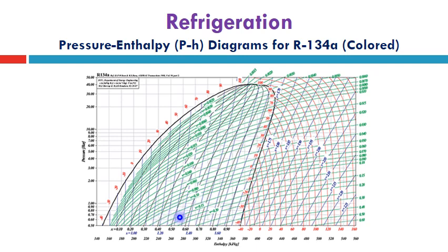And then we can find the constant temperature lines, which must be plotted here as vertical lines due to constant Cp as mentioned before, but its values are shown here starting from 0, 10, 20, 30, and here minus 10, minus 20, minus 30, and then it continues here again on the saturation vapor line starting from 0, 10, 20, 30, 40, 50,